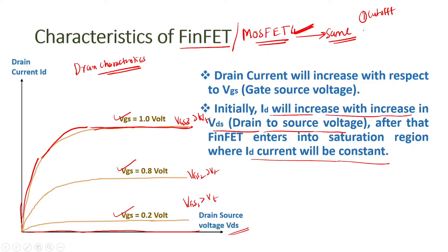Okay, and next it is operated in the linear region. That means the channel is uniform and acts as a resistor. And next we already saw the non-linear region. The channel becomes non-uniform, the rate at which the drain current increases will decrease, and the channel will be pinched off, and after that the pinch-off point will move from the drain end toward the source end, and that is nothing but punch through.